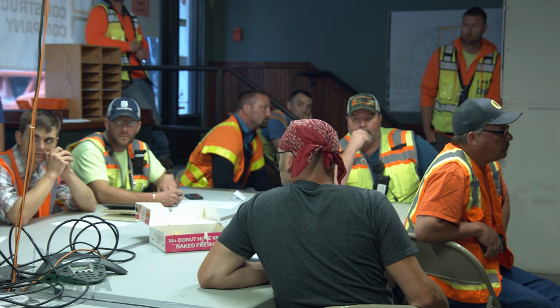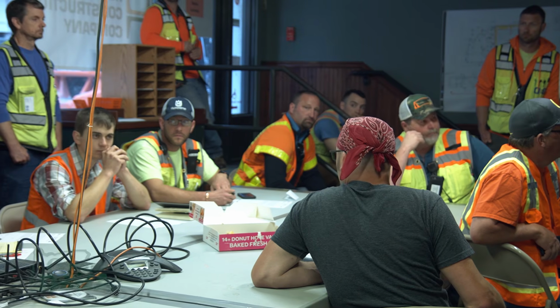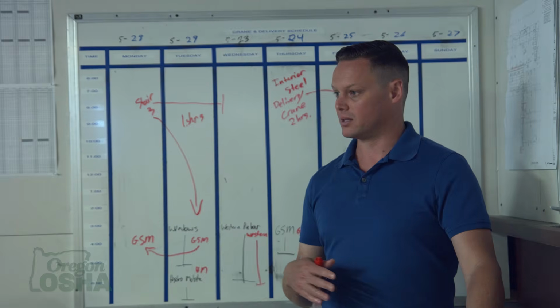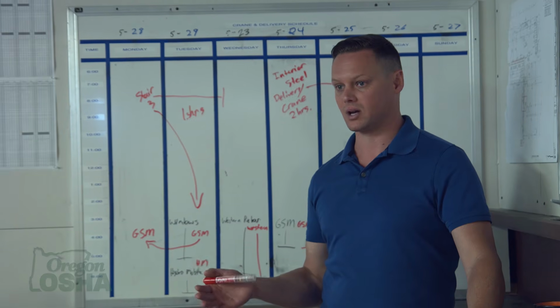Any worker that can be potentially exposed to a fall hazard shall be trained so that they know what the hazards are and know the proper policies and procedures. If they've incorporated a personal fall arrest system, they shall be trained in the proper use, care, and inspection of either the horizontal lifeline, the anchorages, the harness, the connecting device with lanyard or retractable or other.